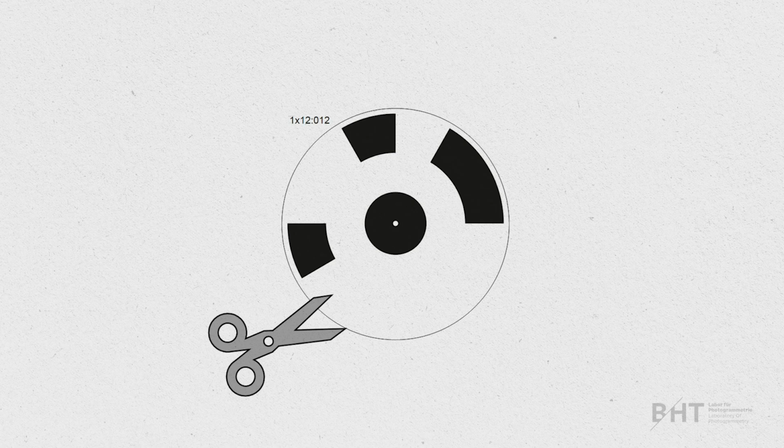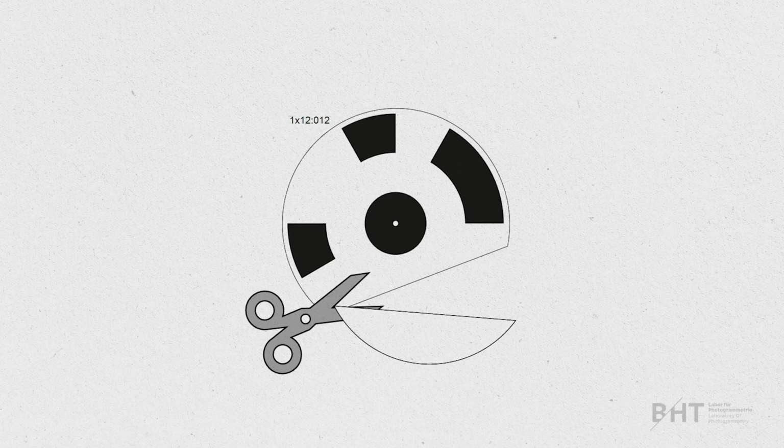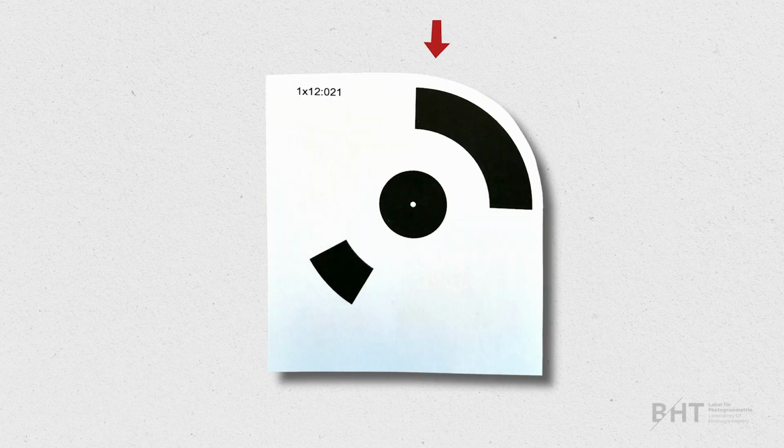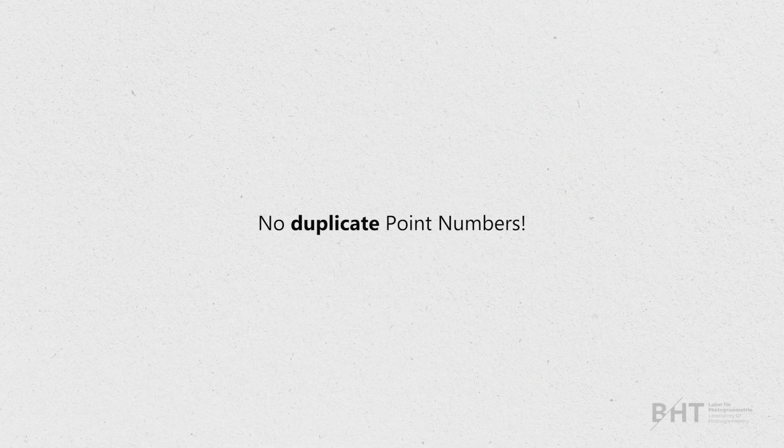Second, when we cut out the markers, we must be careful not to cut through the circle, even if it is white only. The white segments are also part of the binary code. White means 1 and black means 0. Also make sure to leave a small white margin around the code to ensure that the mark is being recognized. The control point is only recognized and measured automatically if the target is large enough and completely imaged so that the point number can be read. Important note: never use 2 or more markers with the same point number. The alignment of the images will crash.